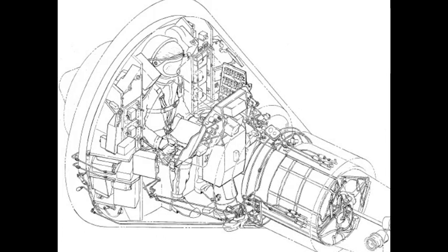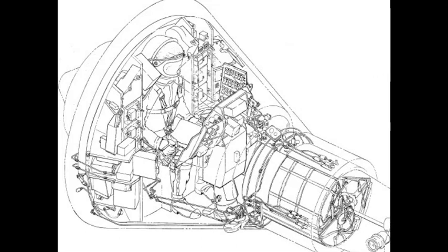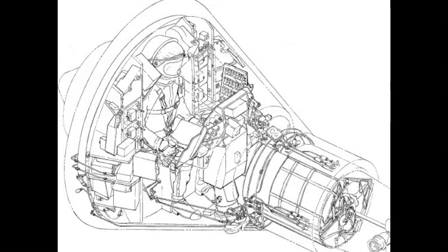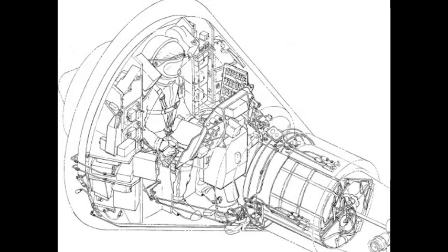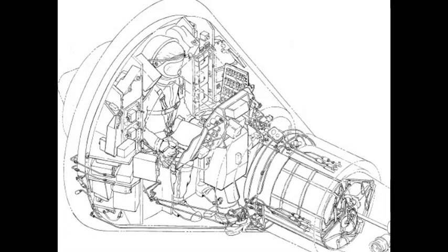2.6. The capsule afterbody conical midsection is constructed of a conically formed inner and outer titanium shell, seam welded together. The outer skin is beaded to form small sealed pressure panels capable of withstanding high pressures and structural loads. The outer conical skin is reinforced with longitudinal hat stringers.